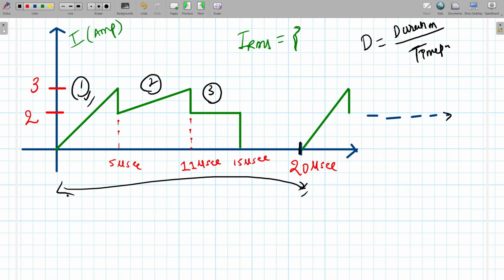Sir, for this wave, what is U? Which one? Second? The first one is a triangle, from here to here it is going. So the first waveform is a triangle. What is the second waveform? For the first waveform, the minimum is 0. For the second waveform, it is 1 by 3 times V1 squared plus V2 squared plus V1 V2. First one is V squared by 3. Second is V squared.